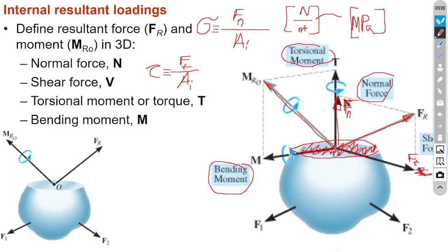If we substitute the true value of the area, not the initial value, then correspondingly the stress is called not engineering stress but true stress.